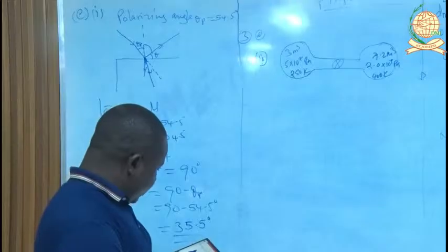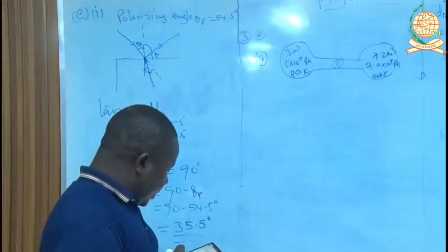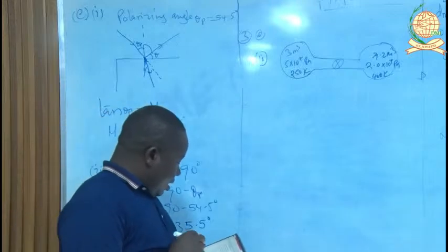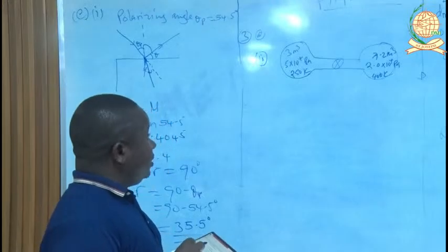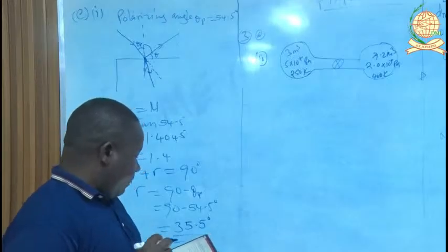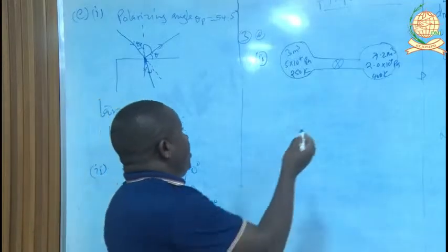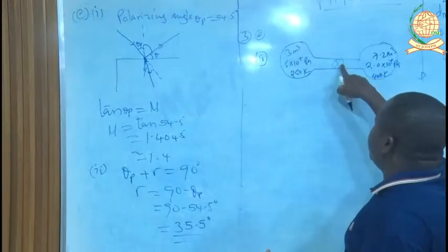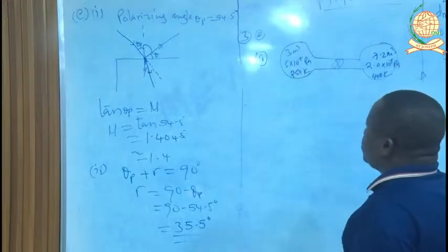Therefore, what is the question? Find the pressure after the tap has been opened and the system has reached equilibrium, assuming that A is kept at 250 Kelvin and B is at 400 Kelvin. That means what will be the final pressure if this cork or tap is opened and the temperature of the two containers remains the same.